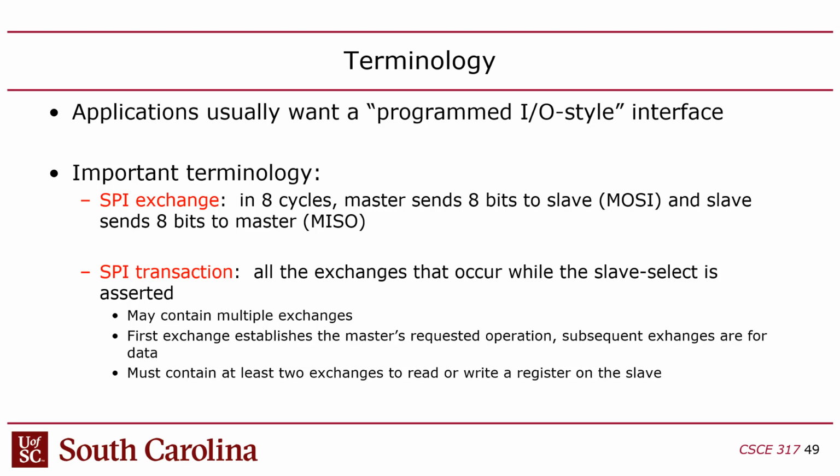So in order to make that work, you have to build another protocol on top of SPI called the transaction protocol. For that, you do at least 2 exchanges, sometimes more. The first exchange is when you send the address, and the second exchange is when you transact the data. If I'm doing a read, I send the address, and then in the second exchange I get the data back. If I'm doing a write, in the first exchange I send the address, and in the second exchange I send the data.